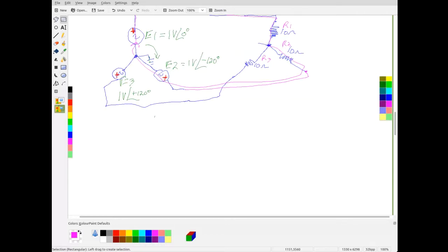If we look at Kirchhoff's voltage law, we go around the loop and we're going to have E1, right? We're starting here at ground, we go up, so we went up E1, that's a positive E1. Then we come over here, there's a voltage drop across this resistor, which is a minus VR1.